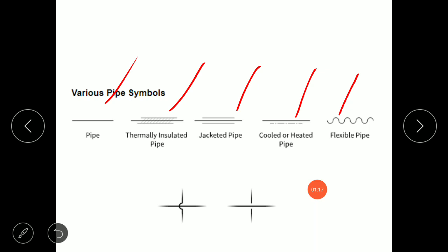Now there are two methods to illustrate when pipes cross on drawings but are not physically connected. Either you use a small hump to show one going over the other, or break one of the lines very near the other to show it going under it. This is not a physical representation of actual pipes. In fact, they may not even cross in the actual system. It is merely a method to keep the lines separate when they must cross in the drawing.